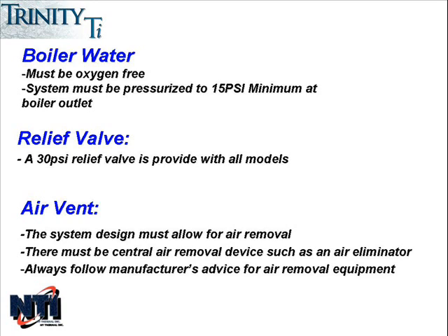A 30 psi relief valve is included with each boiler, but some models are rated to either 80 or 145 psi. You can check the rating plate on the heat exchanger to determine the exact rating of the model you are working with. In instances where the heat exchanger is rated to 80 or 145 psi, a higher psi relief valve can be used instead of the 30 psi version included with the boiler.